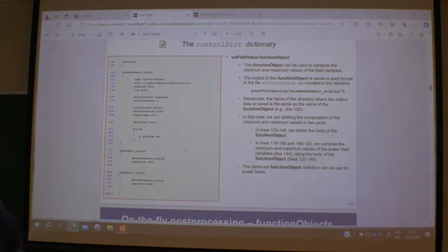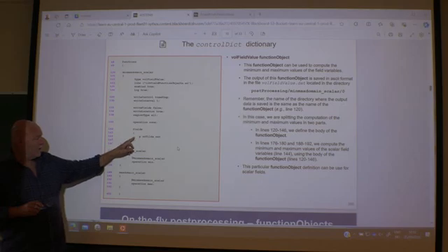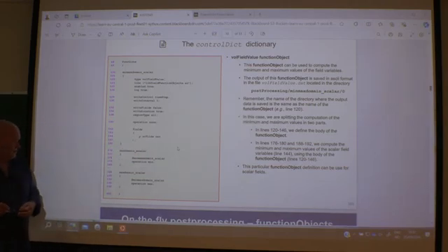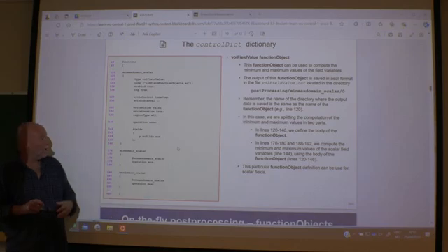So also here you can print out some values from your simulation. Typically you will print out the minimum and the maximum value, here for some scalar fields, pressure, the eddy viscosity. So that's actually an option here, operation minimum and maximum.